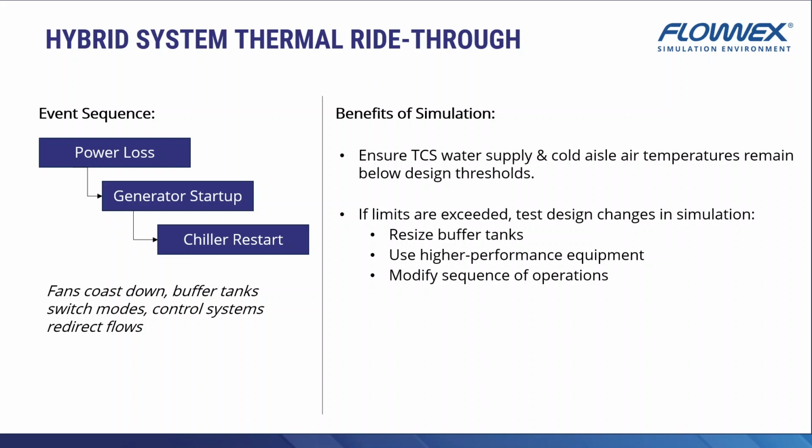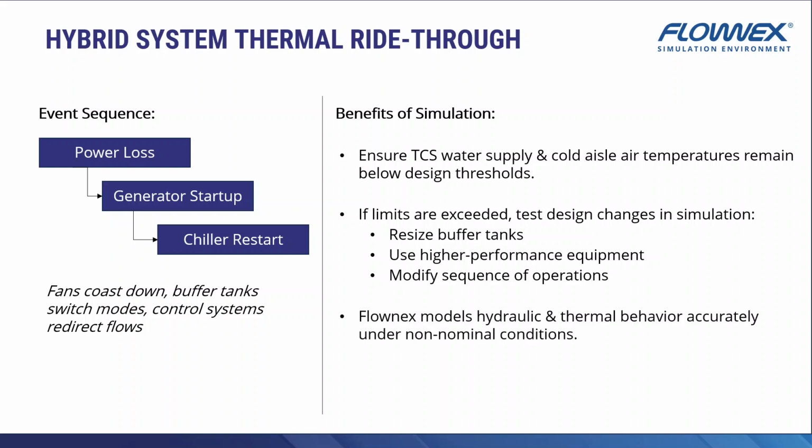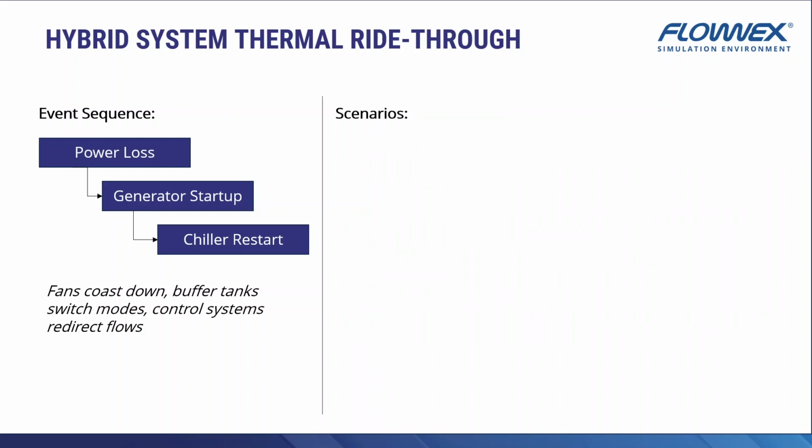Since all of the mechanical cooling equipment is operating well away from nominal design conditions during a thermal ride-through, it is very important that the simulation tool which is used models hydraulic and thermal behavior correctly at a fundamental level, which is exactly what Flownex does. To demonstrate this, we modeled 2 thermal ride-through scenarios at maximum IT load under worst-case ambient conditions, with all the chillers running and no free cooling.